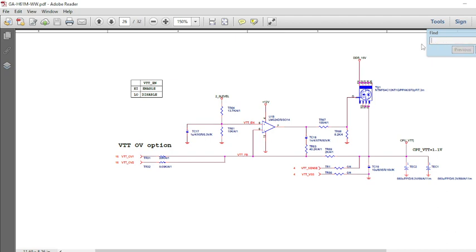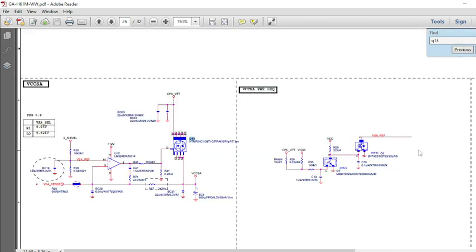After that we are going to check VCCSA, and this VTT power good is enabled for our VRM IC, so this is the most important. So we are going to check VCCSA. Again, as you can see, LM324 is going to control. This is the last op amp of that IC which controls CPU VTT. VCCSA is a sub component of CPU VTT, that's why CPU VTT is given as an input.